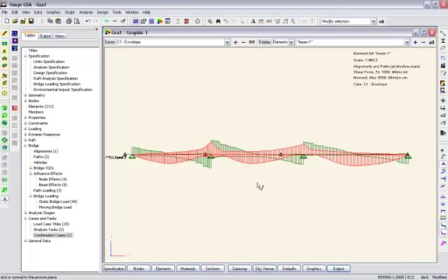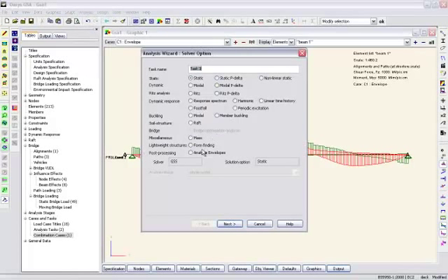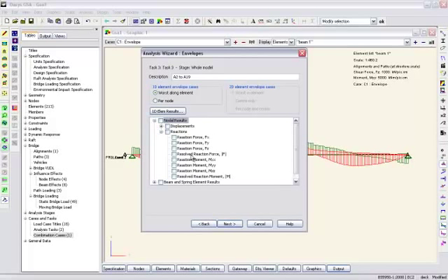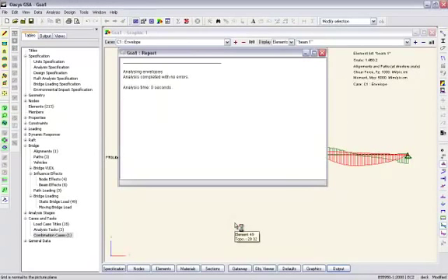Now, as I mentioned, that can take a long while for a large model. So what we have in GSA is an analysis task, which is an analysis envelope. And what we can do here, notice I saved that little list from earlier, and I can say in this analysis I want the worst reaction forces and the worst major axis moments, and analyse that.